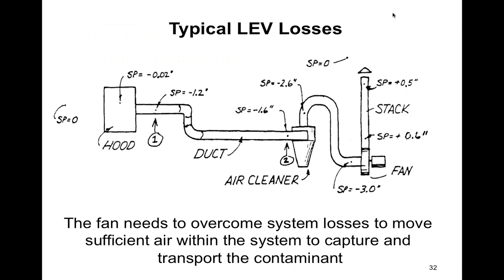By the way, a lot of the stuff that we're saying, that Q equals VA, a lot of this other stuff, applies to almost any fluid. It applies to water or oil just as much as it applies to air. It's just another kind of fluid. The main difference with air is that air is compressible, where a lot of these other fluids aren't compressible. So in some ways, that makes them simpler.